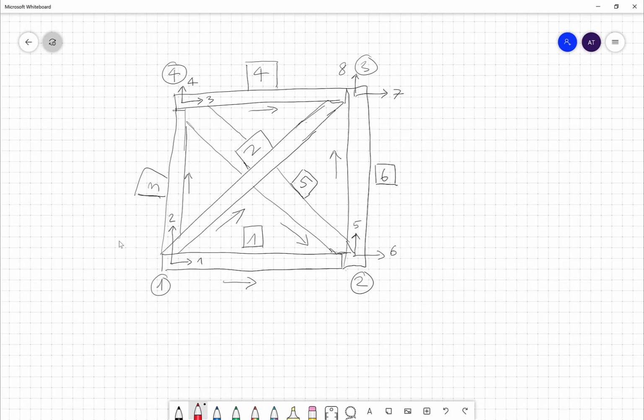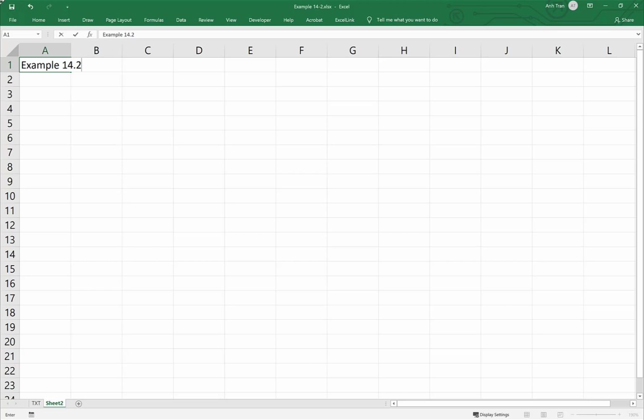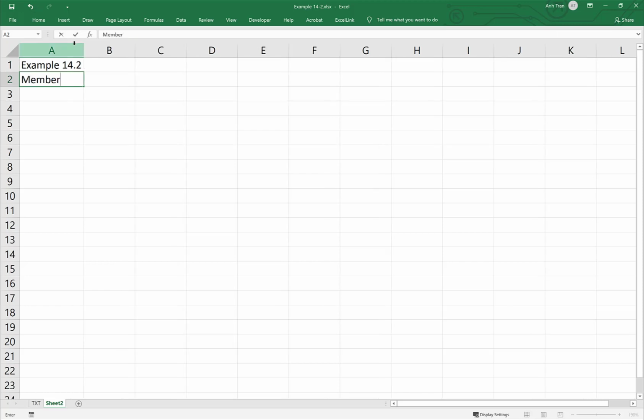In order to keep all the joint coordinates positive, the origin of the global coordinates is chosen at node 1. Now we will make a table for each member of our truss, including their near point, far point, x and y coordinates, their length, their lambda x and lambda y coefficients, and their related degrees of freedom.